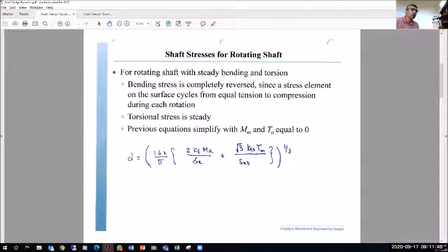Some of you looking carefully here at the SE, the endurance limit, this also, especially the shape factor, would depend on the diameter of the shaft. So this typically would be less than 1, maybe anywhere between 0.7 and 0.9. So you can start with an estimate when you're calculating an SE and then revisit. Remember, the design process is an iterative process.